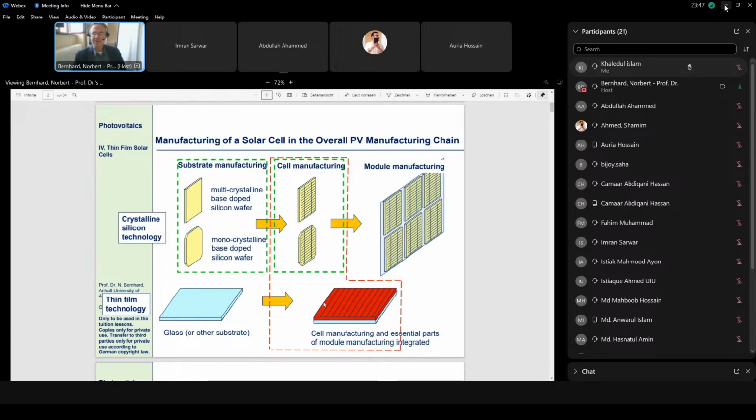difference here is basically determined by a physical quantity which is called the electron affinity, and basically it means the same as the affinities you know from chemistry. And you see both electron affinities are roughly the same. That means the band edge is roughly without any step.